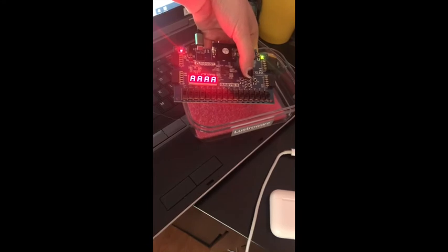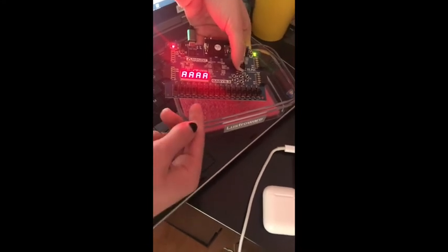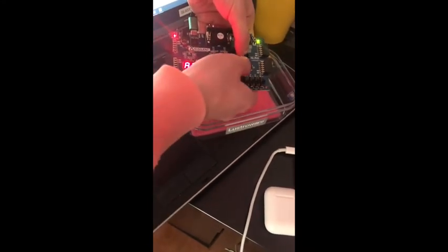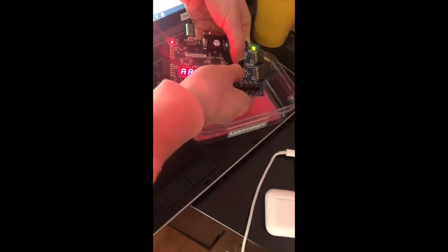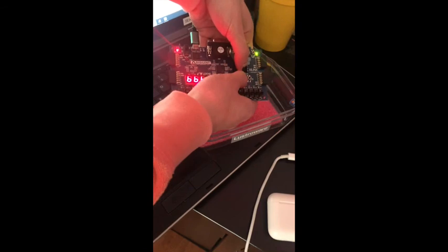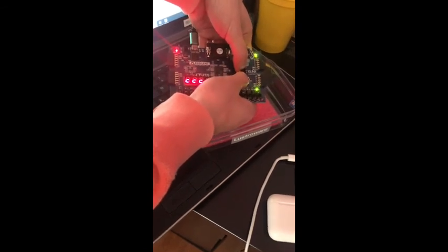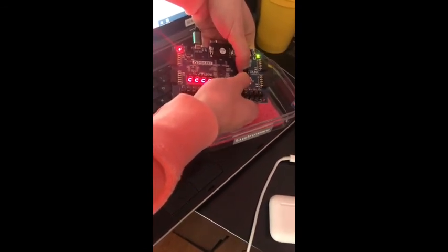And last of all, we have the case where you put in a dollar and a quarter at the same time. You'll get a soda because you put in a full dollar, but you will also advance one state. B state and soda, C state and soda, D state and soda, return to the A state and soda.